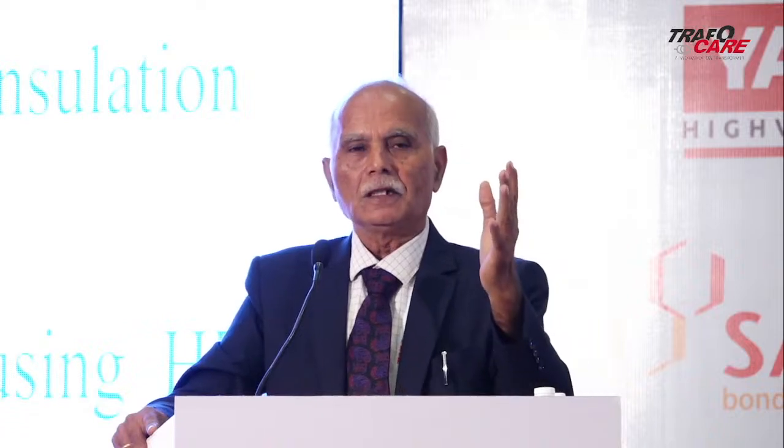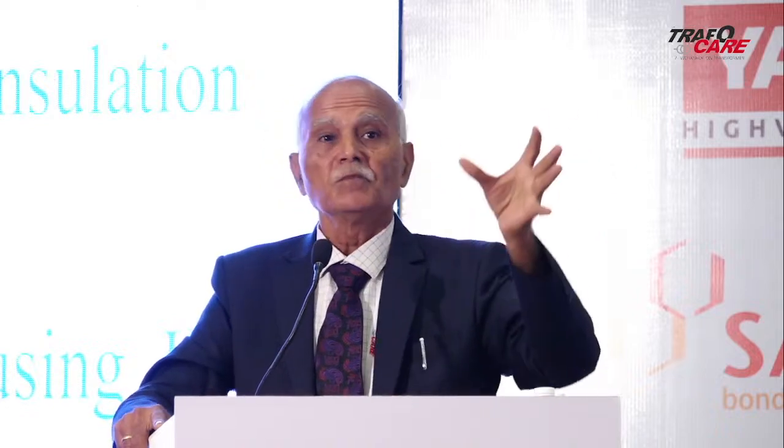So this technique is an indirect technique. It is not intrusive, and along with the dissolved gas analysis, we can do this by testing the oil only. So we get very reliable, accurate information and assess the condition of the solid insulation without any extra effort. Whatever oil samples are coming, we can use for this testing also.